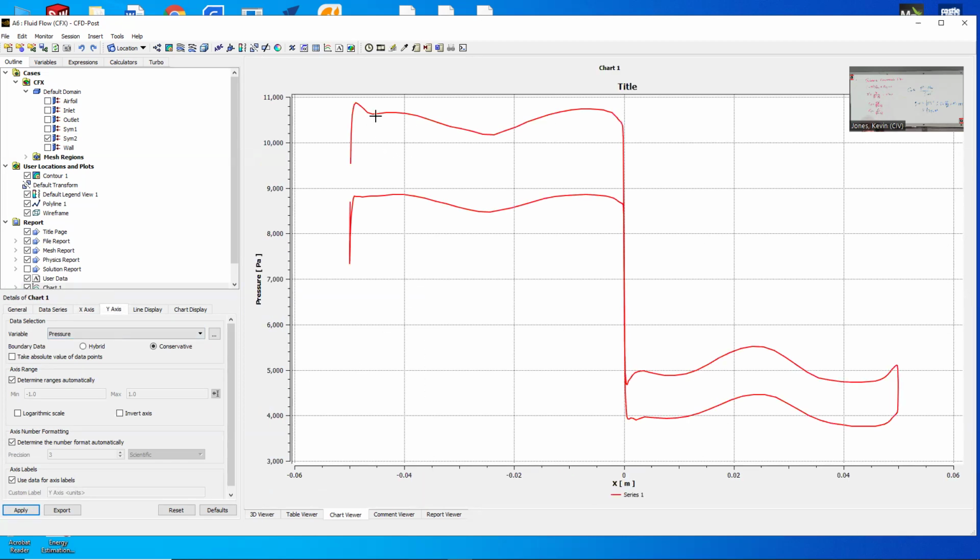So it should be constant pressure on those faces, but it's not. It's messy because we get all these ripples. And you know, Gibbs phenomenon is when you have a discontinuity in a solution and you try to numerically move across it, you get these crazy oscillations. So here are the oscillations, and it just takes a long time to damp out. It doesn't really have a chance because the cells are so big.